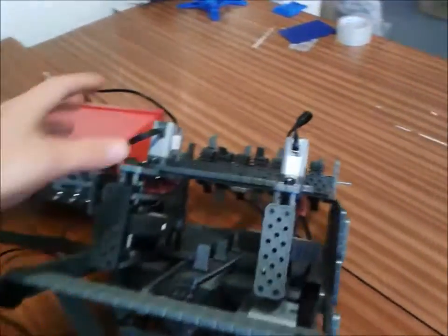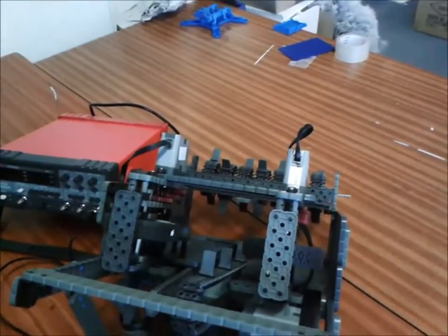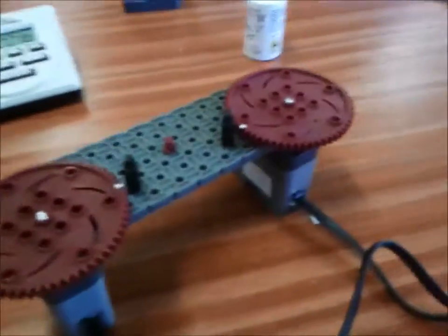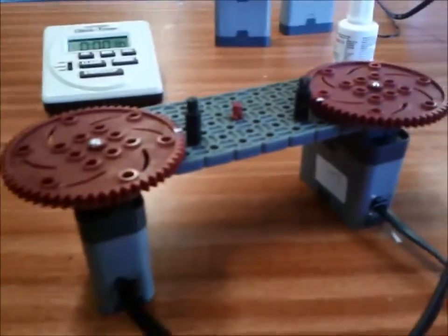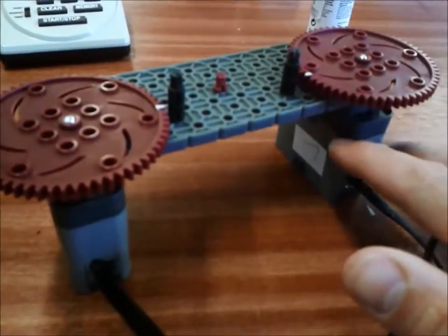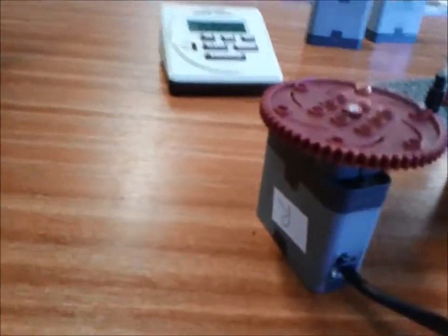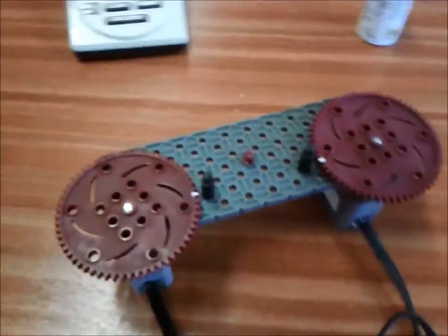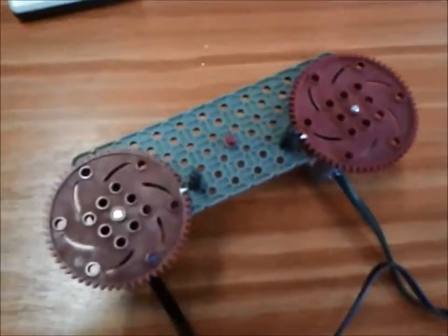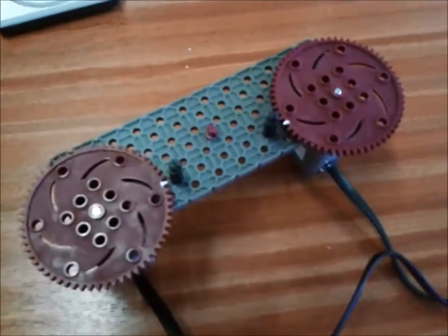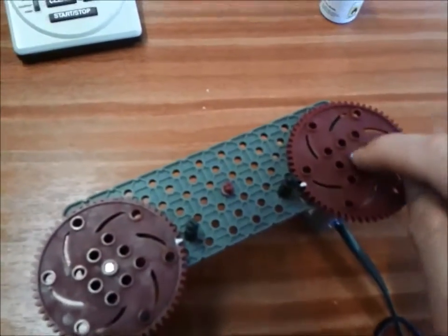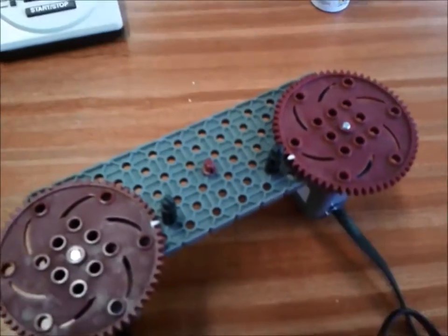So the first thing I'm going to do is take these motors off and connect them up to a little test bed that I've built. Right, so this is my test rig, just to check the no-load speed of these 2 motors. I've got the left motor off my launcher here, the right motor off my launcher here, and I've hooked them up to this really simple little test bed, which is basically just 2 of the large 60-tooth sprockets, 60-tooth gears, and they're connected directly to the drive of the motor. So it's just 1:1. This shaft goes directly into the output drive of my motor.